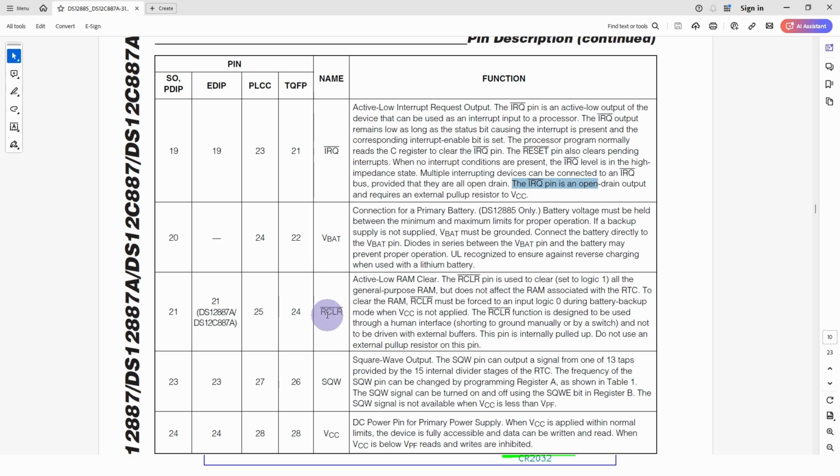So on our design, if we actually short out the pin to ground when the power is off, then this will clear the CMOS RAM should we ever get any sort of corruption, or we want to show what happens on the boot up to see whether or not the checksum matches and whether or not it goes into the CMOS setup.